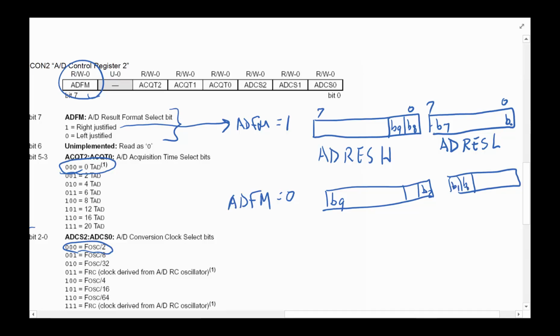So you say, why did they do that? What good is this? Well, they wanted to give us 10 bits, and you have to divide it into 8 and 2. That's the only way, because we got a byte and somehow we got to spread it across. And I think this is kind of nice. Sometimes you want accuracy. If I want high accuracy, but I have a smaller range, but I want to really see the higher accuracy, then maybe this is the right way to do it. Sometimes I don't care about accuracy.